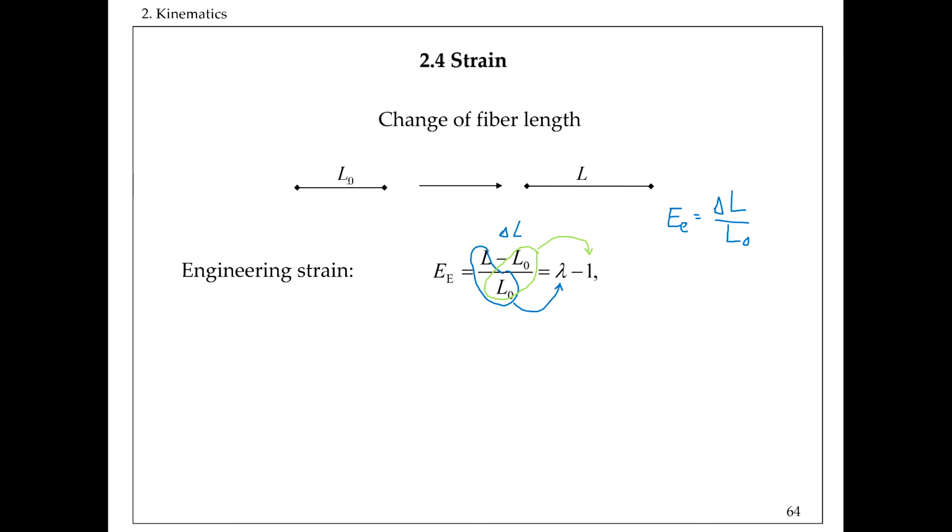So I will use this definition of strain locally and just integrate over the length of this fiber, and I hope to get the same result as the engineering strain, because there is no inhomogeneous distribution, every point feels the same, so they all deform the same, and that's where we started and that's where we ended. So I'm just integrating, maybe I'll get the same result.